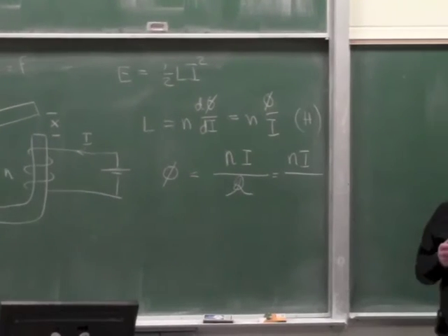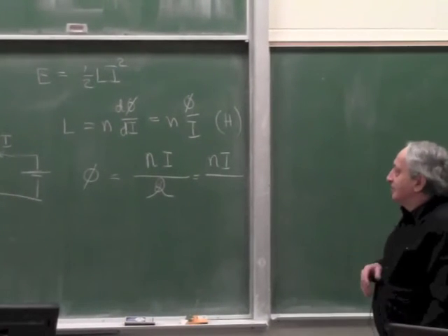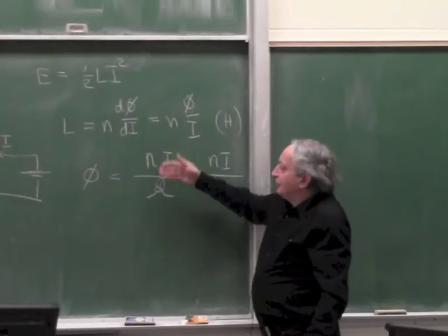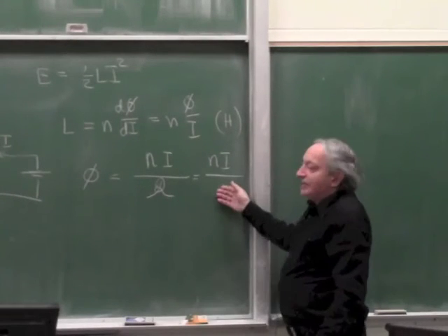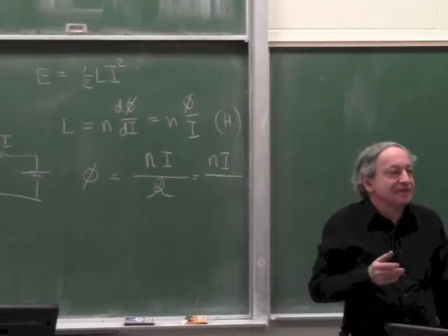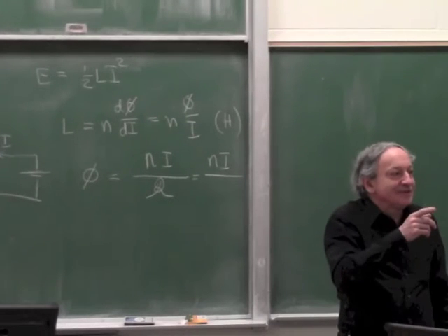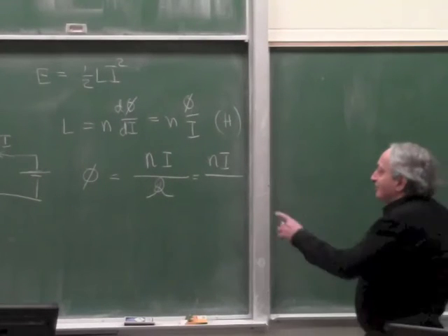What is the formula of reluctance? It's very similar to Ohm's law. In Ohm's law, the current is V over R. Here it's Ni over reluctance. So what is the formula for reluctance of a magnetic circuit? Length over mu naught times mu times A. Good, very nice. Okay, so the same as Ohm's law.